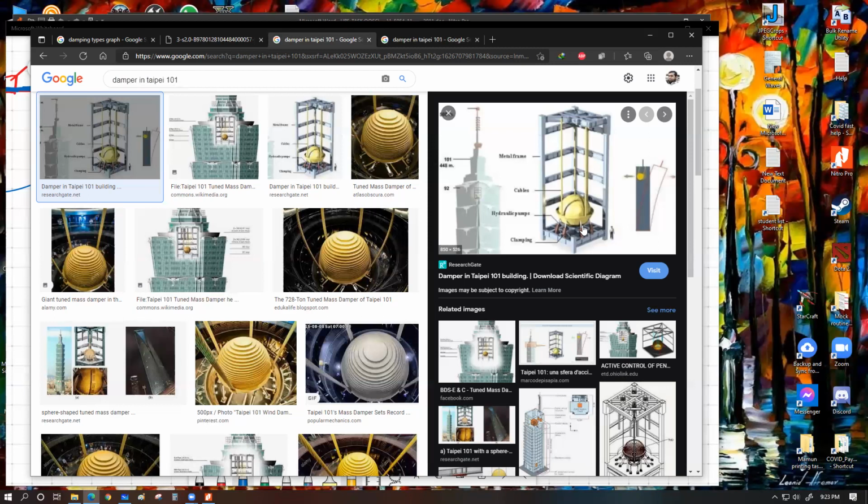Now you might wonder, well, the sphere moves to the right now and the building is at the center. Now the sphere is on the right, so the sphere is going to then start to slowly move to the left. What's going to happen then? If the sphere starts to move to the left, then the oscillation should continue. That's exactly where these shock absorbers come in.